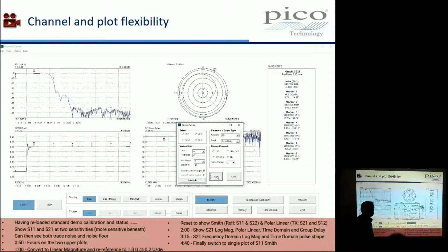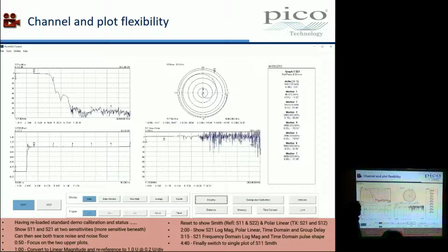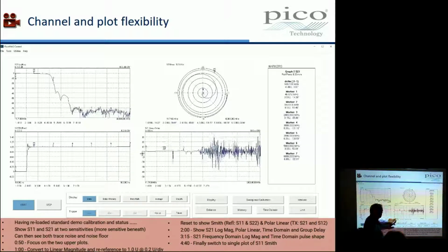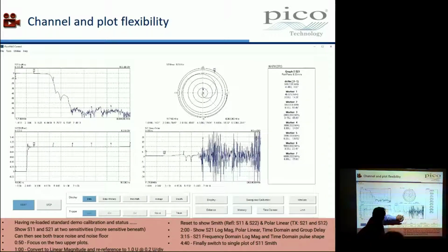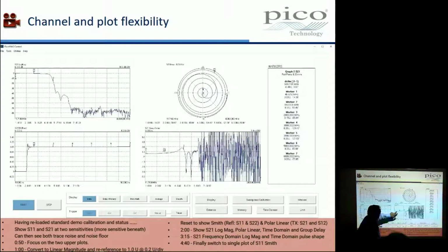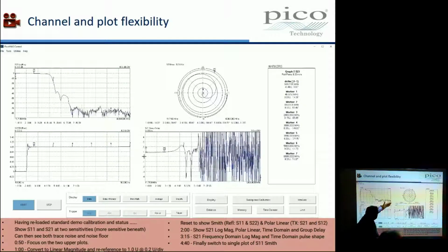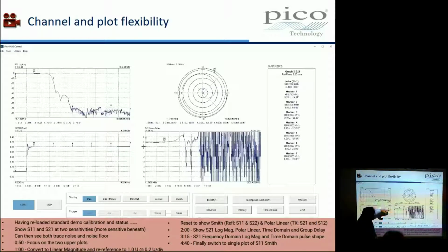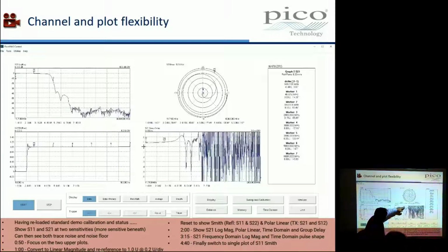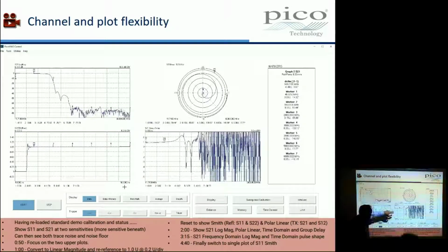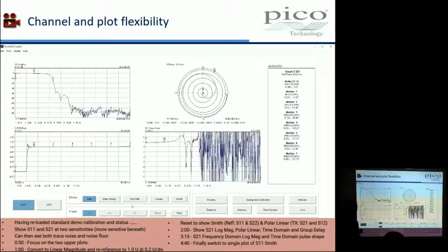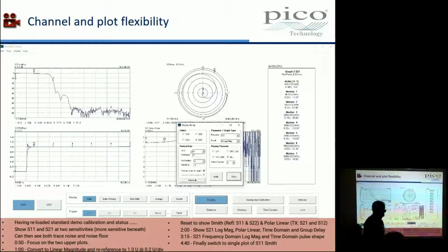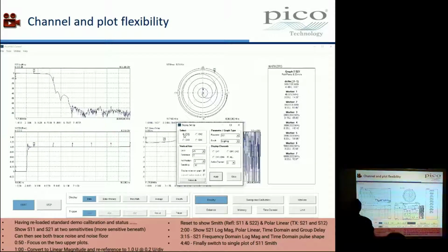Channel 4 S21 group delay. Here we go. So now what's happened here is I've still got frequency along here, but this is a time axis now. Just going to pull out the sensitivity here. And what this begins to show me is that delay is rising and then falling, and you can see that more or less aligns with the roll-off point of the filter. And as we said earlier, that's differentiated, or the slope of phase change with frequency.